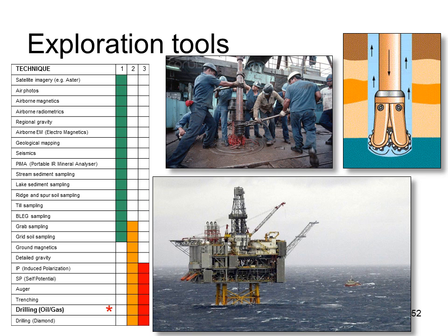Drill holes are large diameter, usually 5 to 36 inches in diameter, and can attain a depth of up to 25,000 feet. They're usually fitted with steerable bits, which allow deviations of the hole to turn the hole in a certain direction or to flatten it to horizontal. Once a production well is drilled, the rig is replaced with a much simpler production platform.